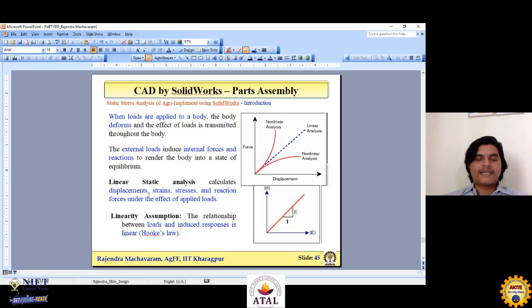Once the factor of safety plot is there, we can check whether the design we have made will sustain the load or not. Theoretically, the factor of safety should be more than one for a better design. Normally, we consider a minimum of 2.5. But if you go with a higher factor of safety, there is another aspect: the increase in cost due to the addition of material.